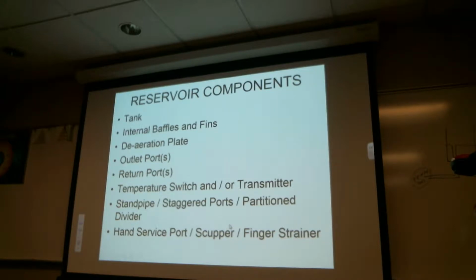So again, if you open the reservoir cap up with the intent of servicing, and you maybe in an area where there's fodder or something that might get in the reservoir, hopefully that finger strainer will prevent gross contamination from getting in. Okay, so that's why it's there.